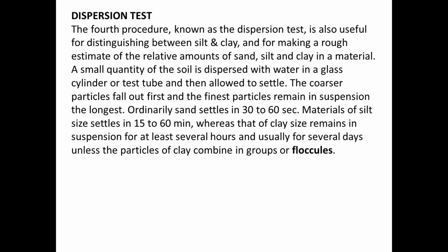Let us have now the fourth procedure, known as the dispersion test. It is also useful for distinguishing between silt and clay, and for making a rough estimate of the relative amounts of sand, silt, and clay in a material. A small quantity of the soil is dispersed with water in a glass cylinder or test tube, and then allowed to settle. The coarser particles fall out first, and the finest particles remain in suspension the longest.